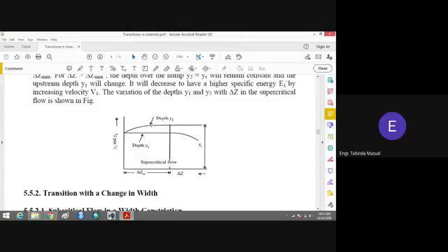And how does the depth of the flow get increased? It increased due to the hydraulic jump. Okay, so you can see that on the x-axis we are increasing the height of the hump, and here you can see that the depth of the flow is increasing, and it will increase till this situation where we will get the critical depth of the flow. This is the critical depth of the flow. This YC is with this indication, okay, with this line. This shows you that here we have the critical depth of the flow.